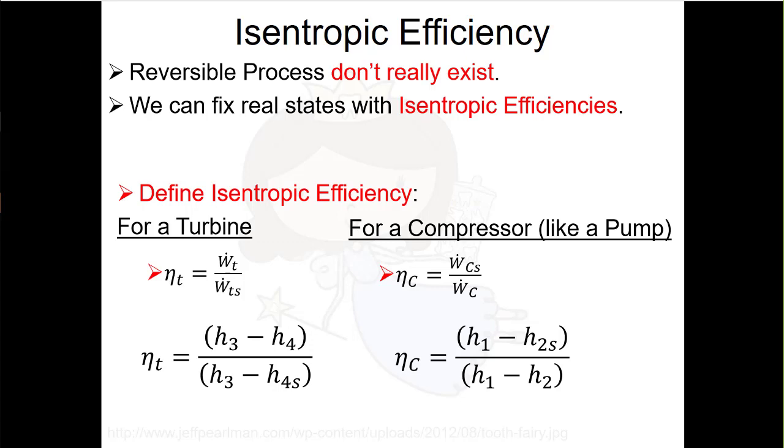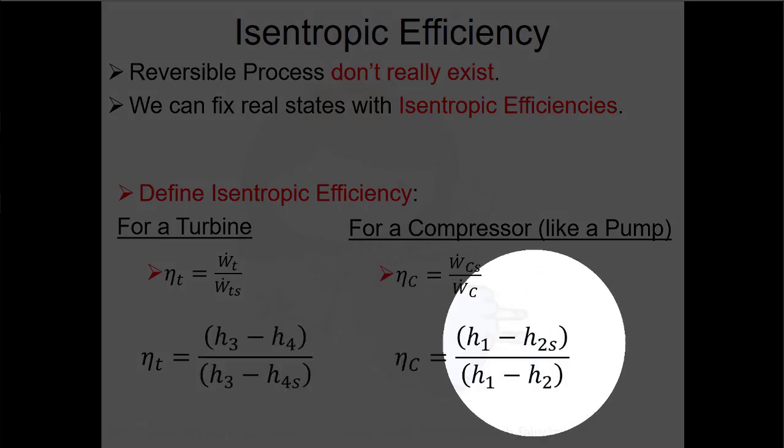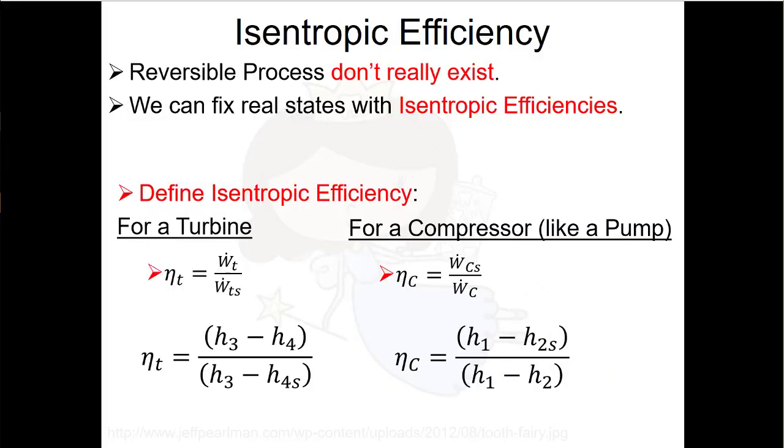If we get the expressions that we expect and things are numbered the way they typically are in the textbook, then these would be the expressions that you get if you can make all those assumptions that we usually would make here. Here we still want to be able to identify the isentropic outlets, the ideal outlets, because even if we don't need the ideal case, we're going to use the isentropic efficiency to get to the real case. And we have to remember that to get these isentropic outlets, we're going to have to use our special isentropic relationships because the working fluid is an ideal gas.